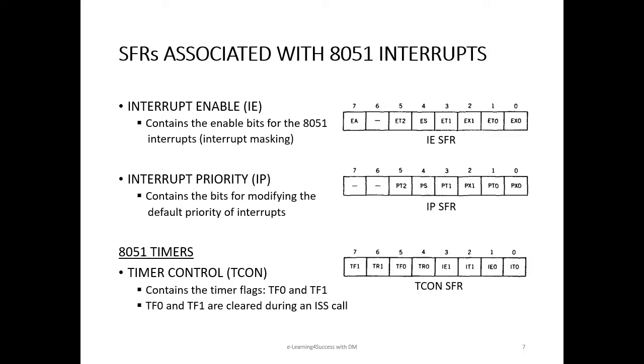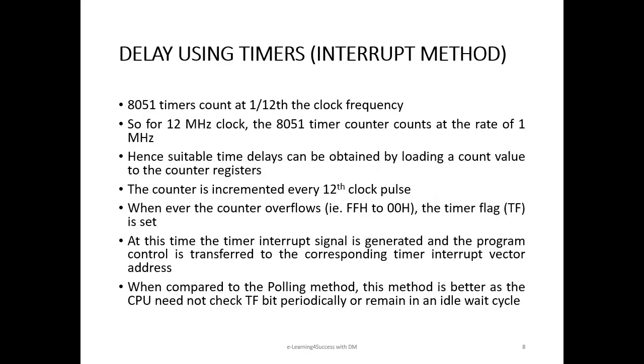However, you should note that the flag bits TF of TCON special function register will generate the corresponding timer interrupt signals. This flag is cleared automatically when the corresponding interrupt service subroutine is invoked. Next we will see how the 8051 timer counter module is used to generate time delays. Here we will be discussing the interrupt method.